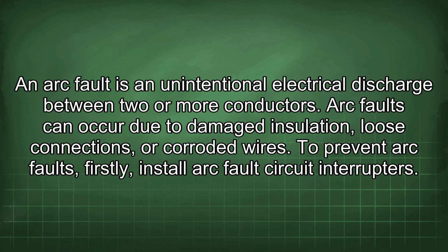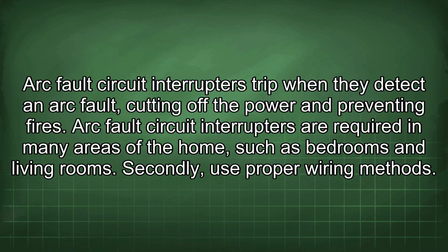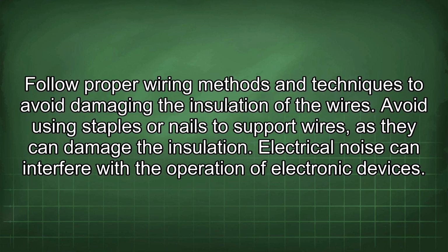To prevent arc faults, firstly, install arc fault circuit interrupters. Arc fault circuit interrupters trip when they detect an arc fault, cutting off the power and preventing fires. Arc fault circuit interrupters are required in many areas of the home, such as bedrooms and living rooms. Secondly, use proper wiring methods. Follow proper wiring methods and techniques to avoid damaging the insulation of the wires.